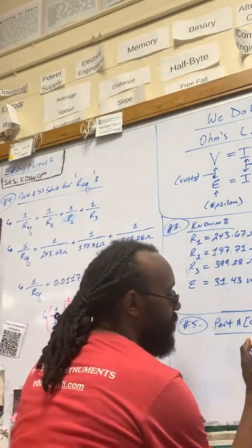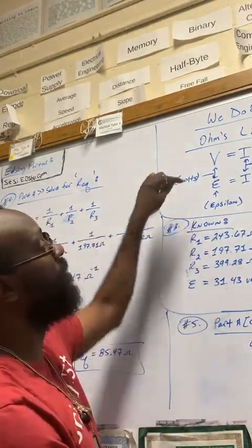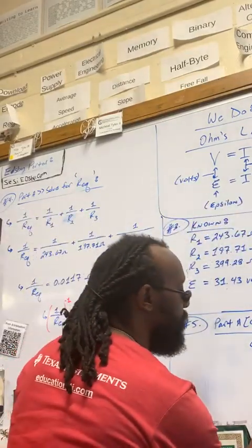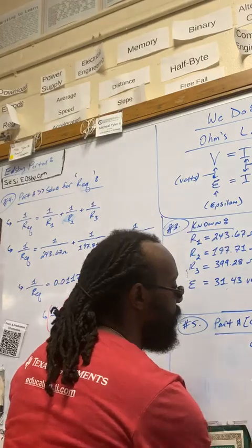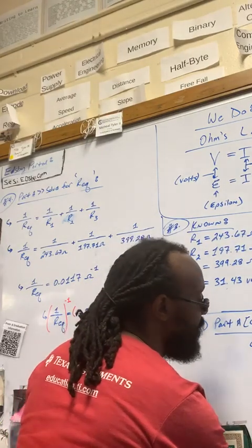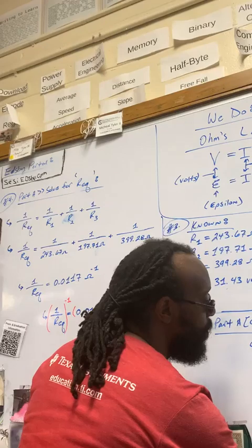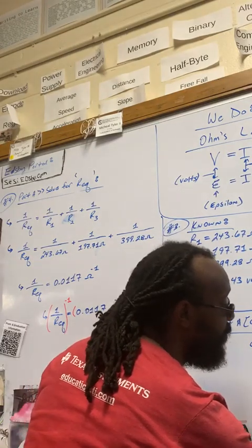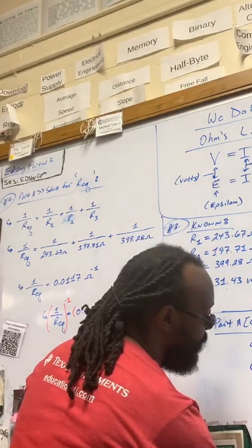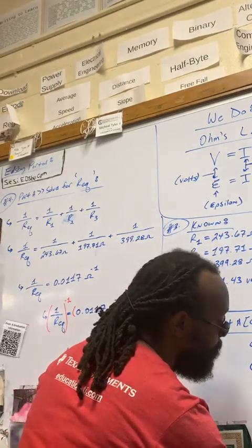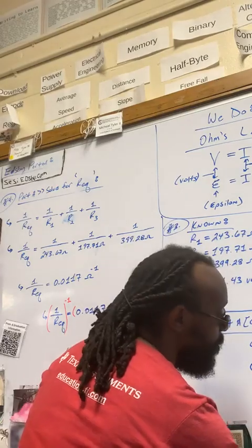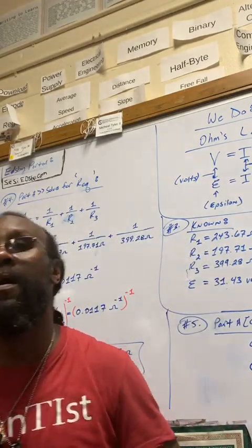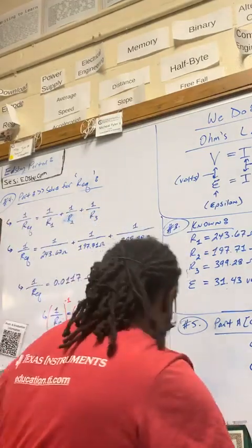That total. All right, so now rewrite the equation for epsilon and get I total by itself using your algebra. So the equation that we're using here is epsilon is equal to I total multiplied by your REQ that we just figured out. Write it again. All right, and then we want to separate REQ off of I total using our algebra skills.